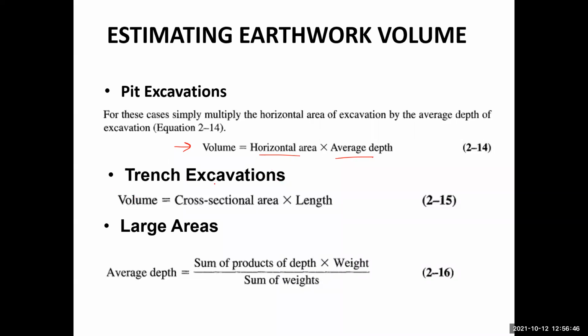For the trench excavation, how can we find the volume of the excavation? It is also simple, similar to the previous case. We can take the cross-sectional area, if we are making the excavation like this. So this is the cross-section. This cross-sectional area looks like a trapezoid, but the excavation can be in the form of a rectangle as well.